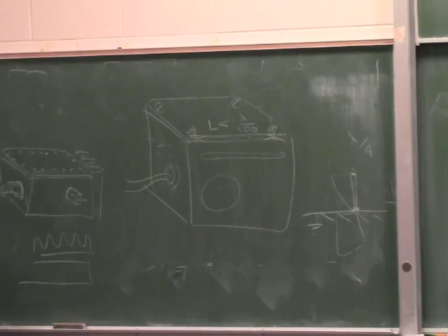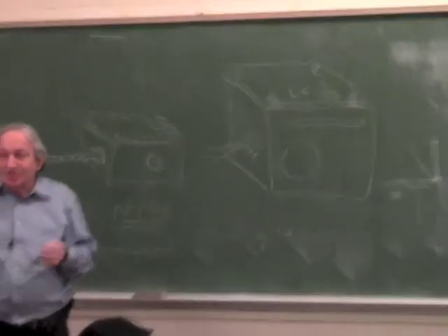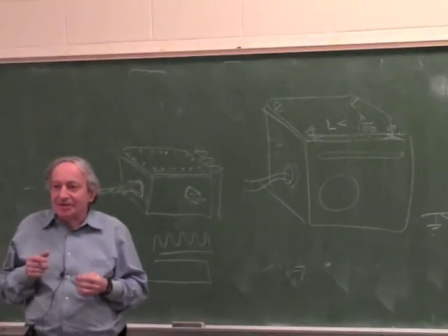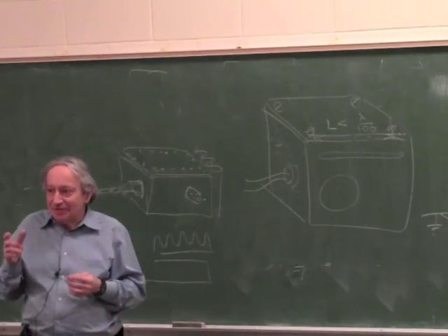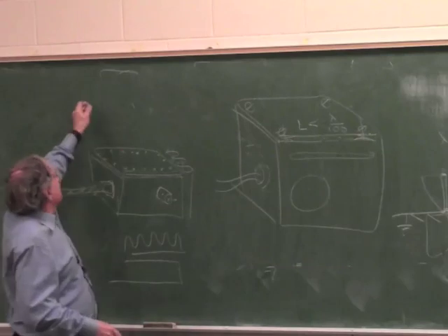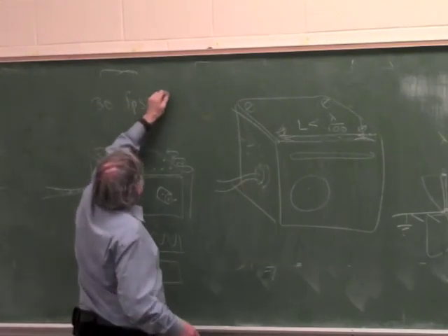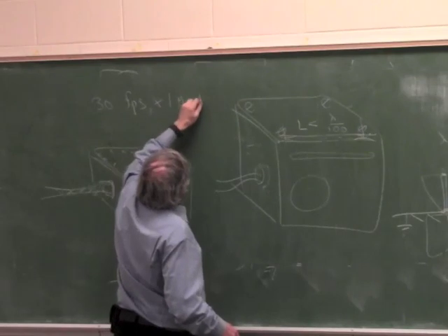The other type you have to worry about it if you use CCD cameras, because CCD cameras have a very high data readout rate. So maybe the camera only takes 30 frames a second, but each frame of the camera is a megabit, right? A normal webcam. So it only takes 30 frames per second, but it's times 1 megabit.